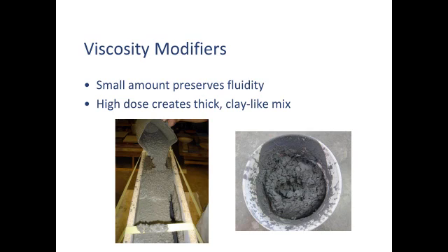So here's the effect of a polycarboxylate. Now these are different mix designs, but they were both very flowable. So the highly flowable concrete is on the left, and then what you're actually seeing is a GFRC mist coat that normally is the consistency of a very runny milkshake that has had a lot of viscosity modifier added to it, and now we have a perfect clay-like mix that can be hand-packed. And we didn't have to add a lot to it. So it can become a versatile tool.